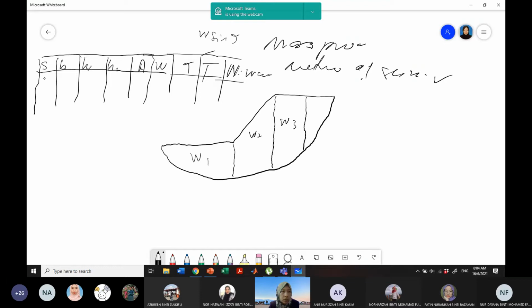So slice number 1, okay, and B, if you measure from here to here, let's say we have 2 meter. When you draw on the graph paper, with 2 meter, we can take a scale like 1 centimeter is equal to 1 meter. And then how do we locate the position of the centroid for this W1? Due to the assumption that this lies in the shape of a trapezoid, you can have the centroid of this slice for W1, assuming that we have a square. So the W will be acting at half of the B. If you have B equal to 2 meter, divided by 2, 1 meter from left, 1 meter from right, this is the position of the W1.